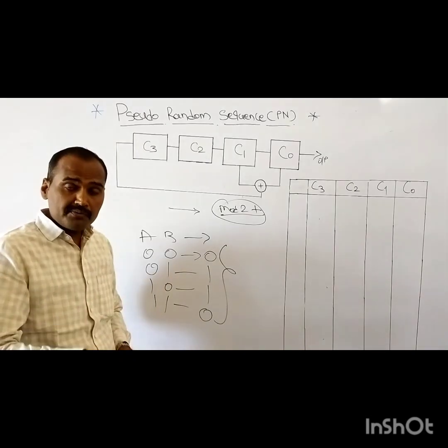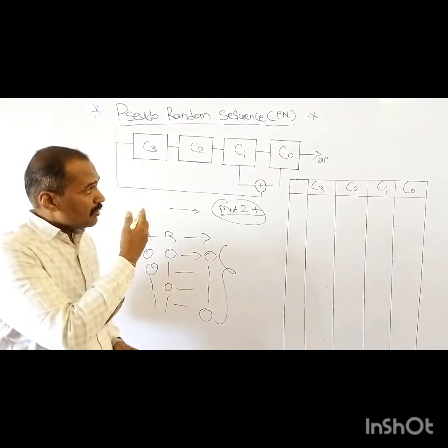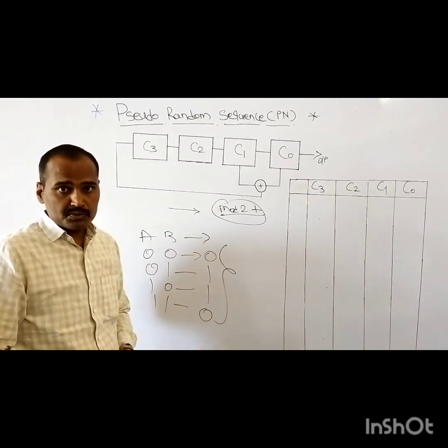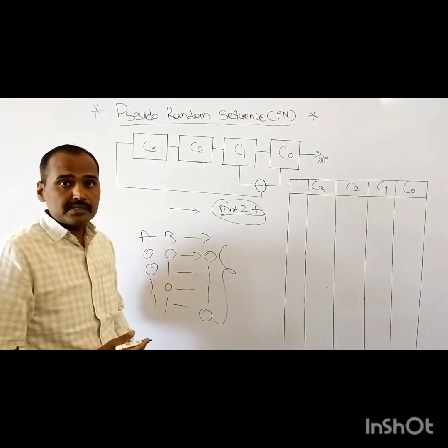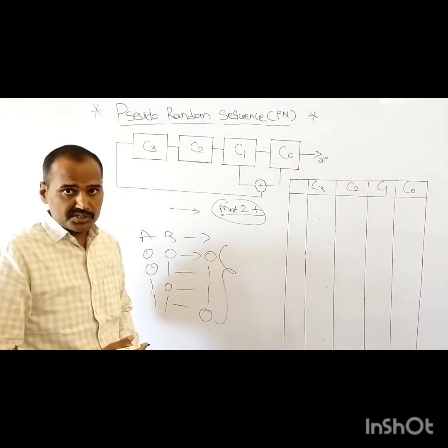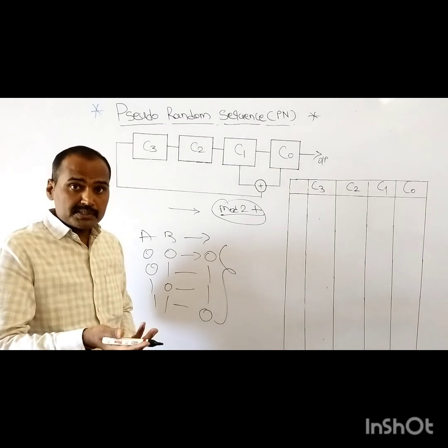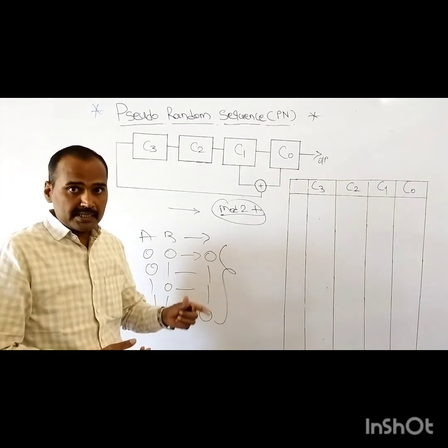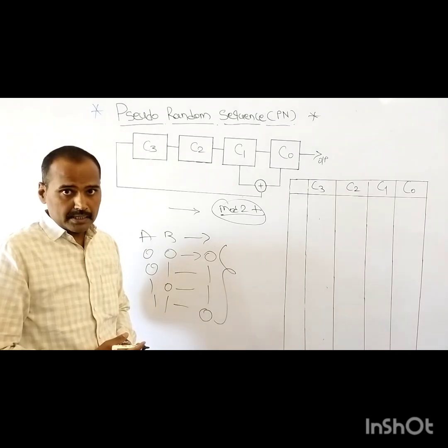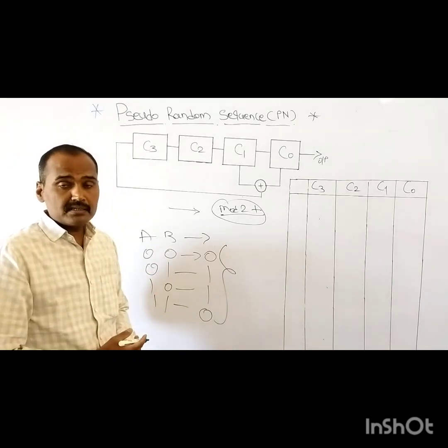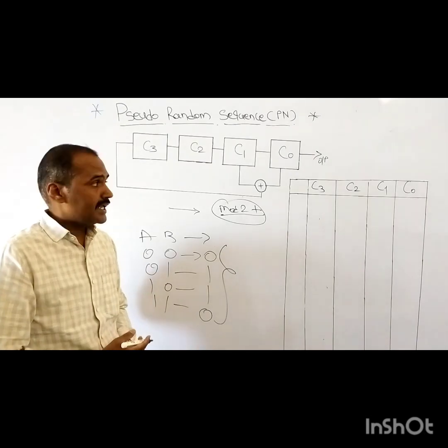Our objective is to know how the desired PN sequence, or spreading sequence, is generated with the help of such a linear shift register structure for the purpose of spread spectrum, because the spectrum spreading is done with the help of this spreading sequence only. That is the basic logic behind the spread spectrum modulation technique.